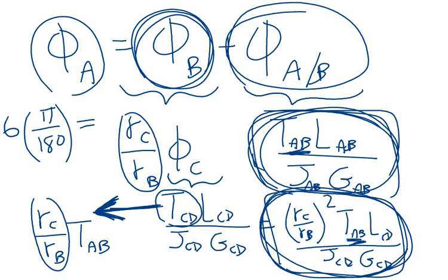Another very similar variation is what I started trying to show originally, which is the torque would be given, but the radii, or the diameter of the shafts, would not be. So now you're going to solve for the radii, or the diameter of the shafts. In that case, the T sub AB would be known. It would be the J value that you're trying to find. The J value, of course, is going to represent the radius of the shaft, and that, of course, is related to the diameter.